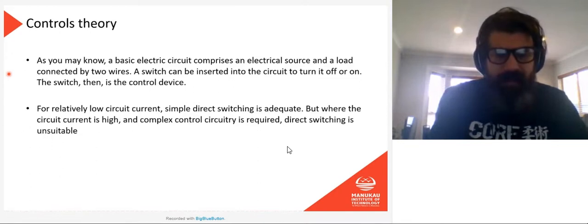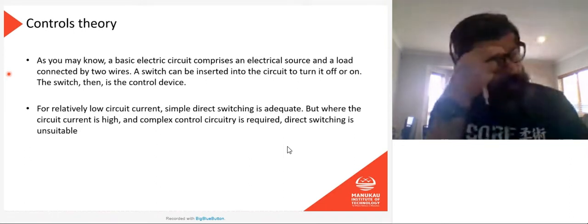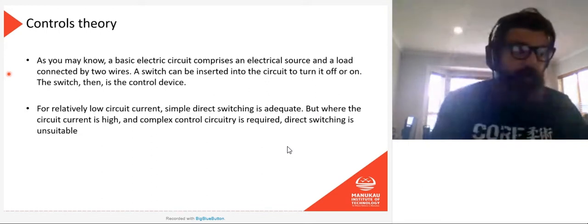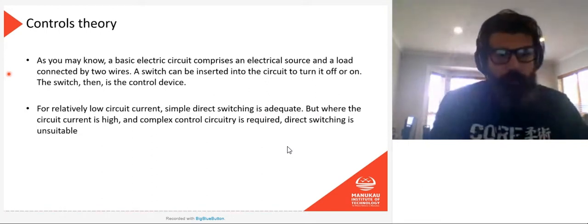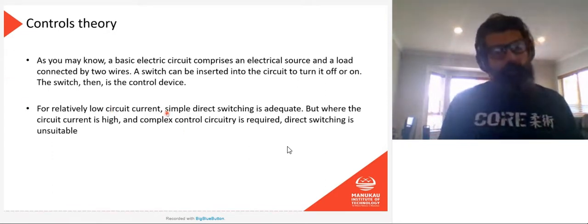It's much more difficult and costly to build a circuit like that than to build a simple stop button circuit. Just use small cables, and all those buttons are doing is switching the power for the coil on the contactor, and then it's the coil which switches on the contactor, and the contactor switches the power for all of those sockets. This is why we would use this kind of method.